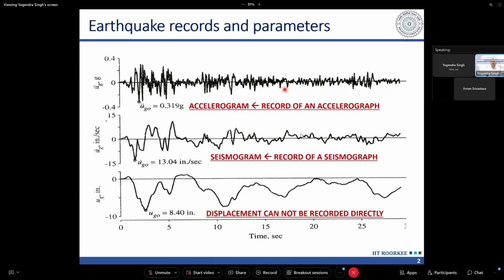So we can't take advantage of that, and that's why we take advantage of ductile energy dissipation only in case of earthquake, and that makes earthquake resistant design so special and a little bit complex, because we have to take into account the nonlinear behavior under cyclic loading.